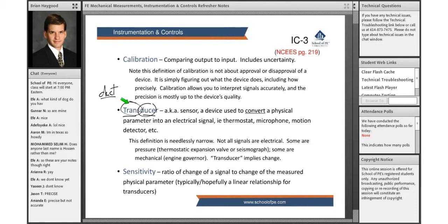It's similar to a word like diagonal, but it's not putting things with things. That would be conduction. This is transduction, which says we're changing it or taking it across something. So what are we changing here? We're going to carry something along and change it. If you have a sensor that picks up some information and converts that into some other kind of signal, then it's a transducer. So if we measure temperature and convert temperature to a voltage or a resistance, that's a transducer.